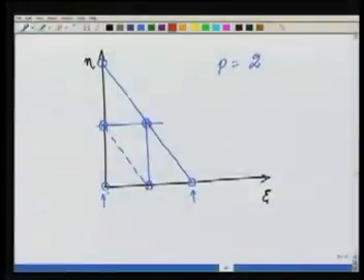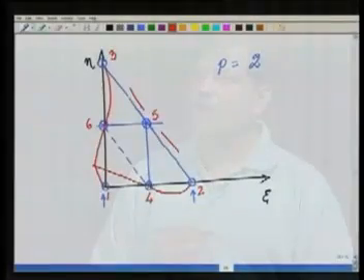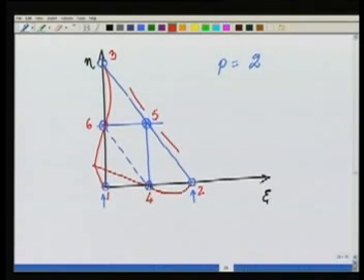So our challenge is, let's say I want to now define n1. So I'll call this node 1. I will do the numbering in a way which is a little different from the standard. 1, 2, 3. This is 4. This is 5, and this is 6. Let's say, if I now want to define n1, n1 will be such that it is 1 at this point, becomes 0 at this point, and 0 here. Similarly, on this edge it is 1 at this point, 0 here, and 0 here. So n1 is a curved roof which gradually dies off to a value 0 on this second edge of the master element.